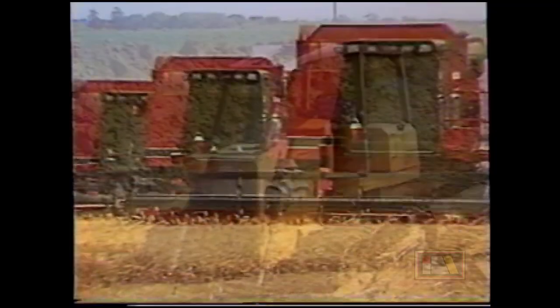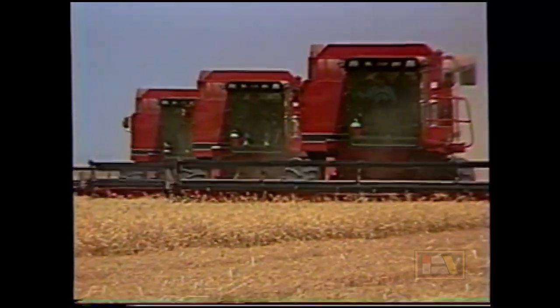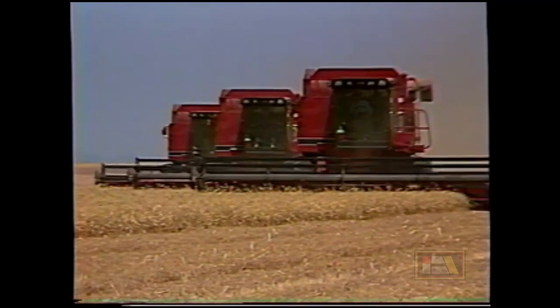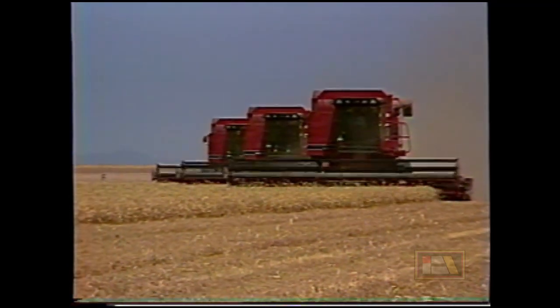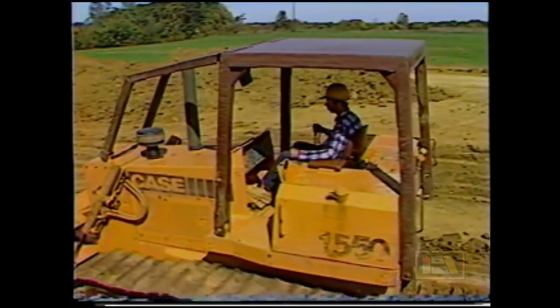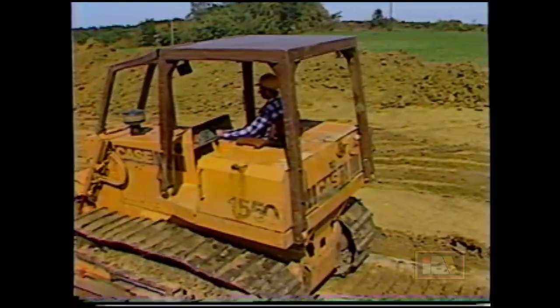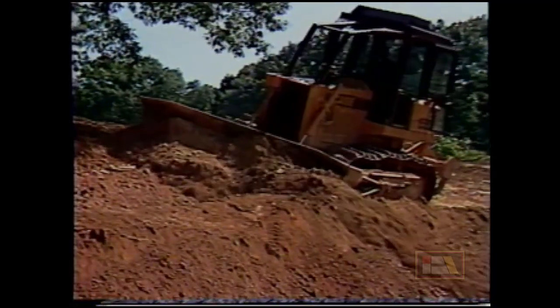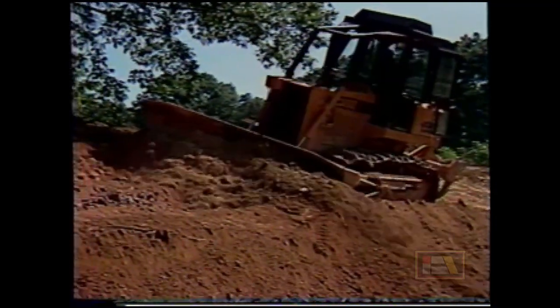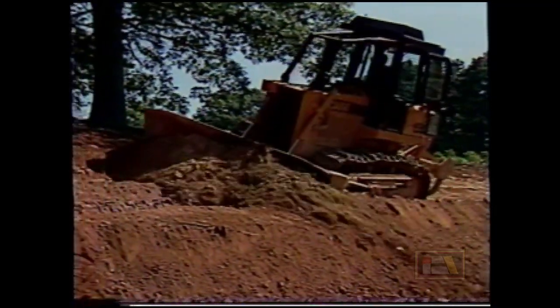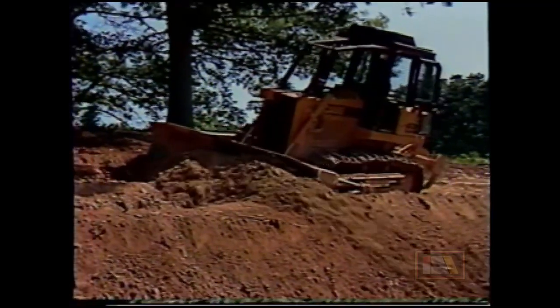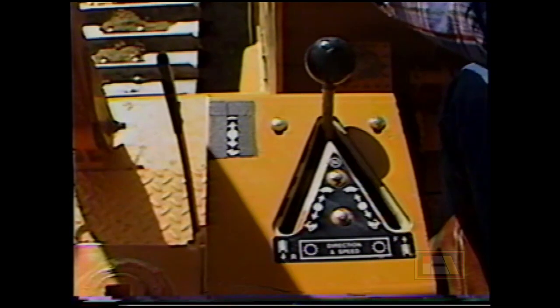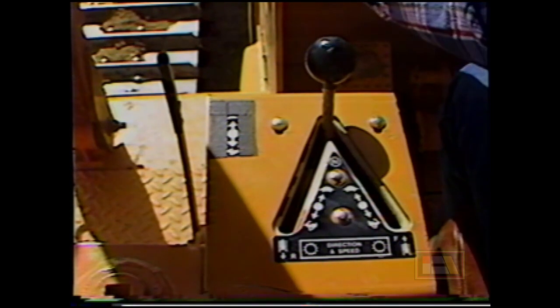The operator has an infinitely variable amount of control over the hydrostatic system which he is operating. So not only does the operator get smooth transitions between directions, he also gets the advantages of a torque proportioning system which compensates for an increase in load demand. However, in order to maintain maximum horsepower availability and maximum control, the engine should always be run at full throttle.